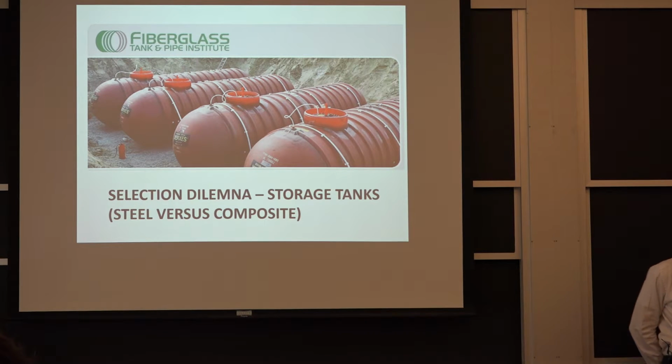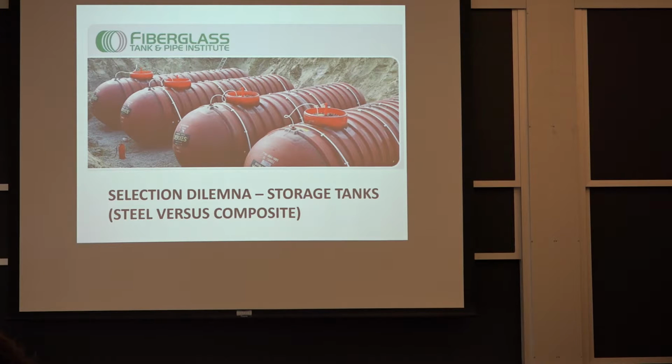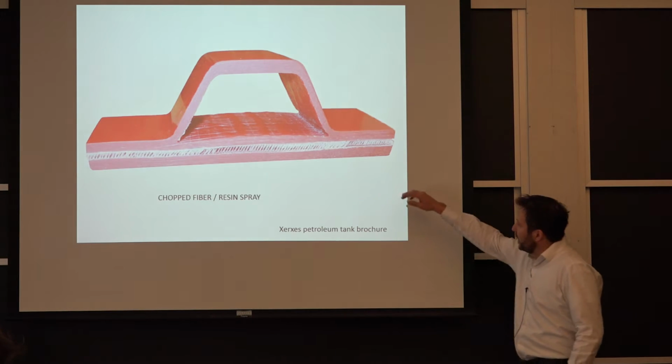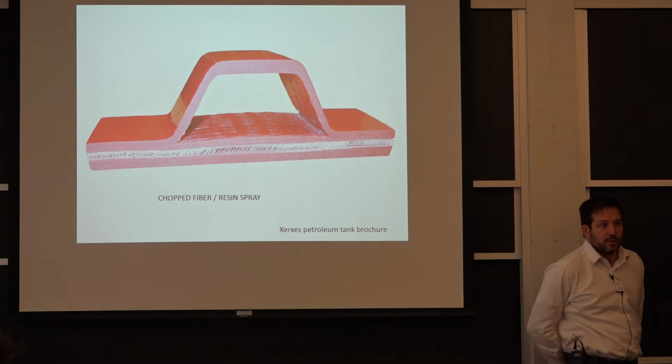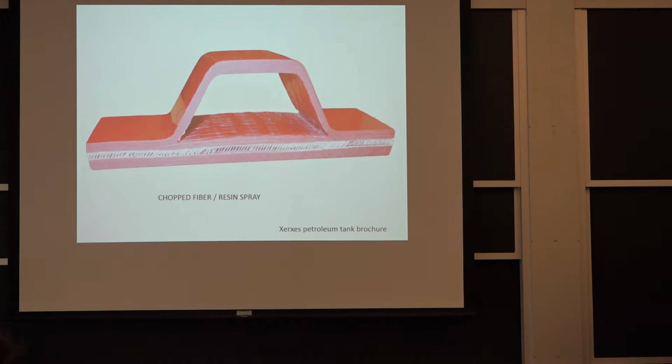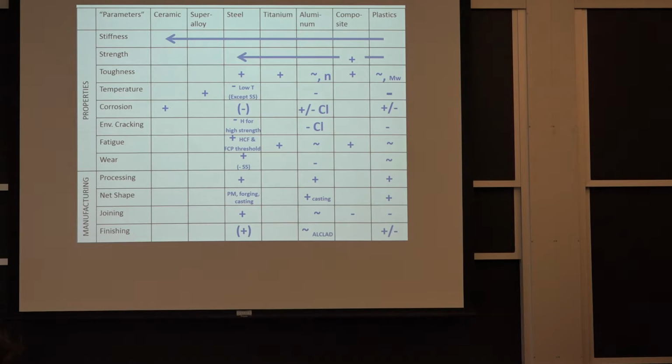It's not easy. But anyway, some of the issues that happen there with the composite is, again, it won't corrode. This is perfect with respect to the interaction with the soil. But the liquid, when people moved from using gasoline to gasoline with ethanol in it, well, ethanol is a different solvent. So they did have issues with some of the polyester resin used to build up that wall, and they had more rapid degradation, depending on the conditions. So going to the plastic doesn't solve everyone's problem.